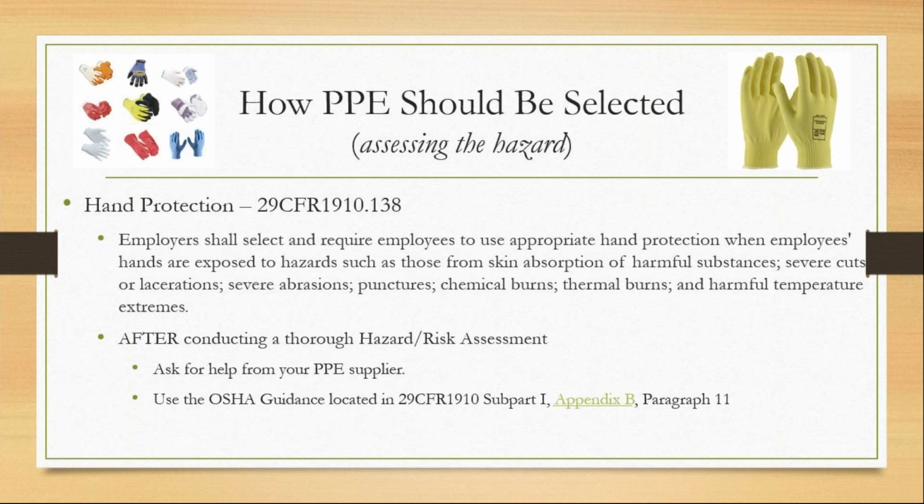Hand protection. Not all hand protection is created equal. There are chemicals in some of our plants where we might have different chemical processes for etching aluminum and doing stuff that might eat up a rubber glove, so you have to select nitrile. There might be some other chemicals that attack nitrile, so you have to select rubber. You might not want to select Spectra because it'll melt, and instead use a heavier Kevlar glove to protect against cuts and burns on the press.